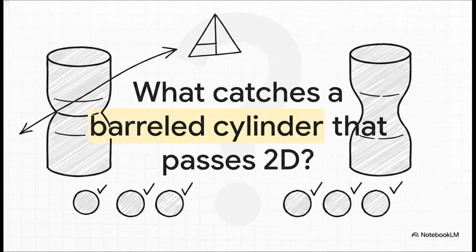So, time for a quick quiz to test your new GD&T X-ray vision. Imagine a cylindrical pin. You check the circularity of 50 different slices, and every single slice perfectly passes 2D circularity. It's round at every single cross-section. But when you look at the pin from the side, it bulges in the middle like a barrel, or maybe it pinches in the middle, becoming what we call wasted. The standard specifically warns that full straightness might not be available in cases of wasting or barreling. So if circularity only checks independent 2D slices, what symbol actually catches a part that is wavy end to end?